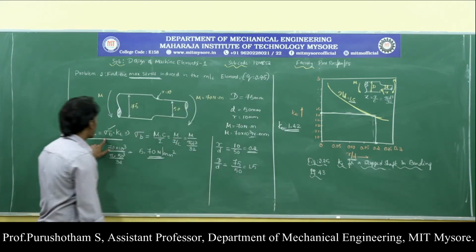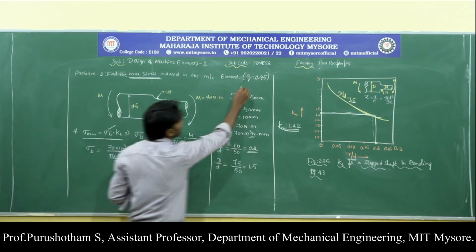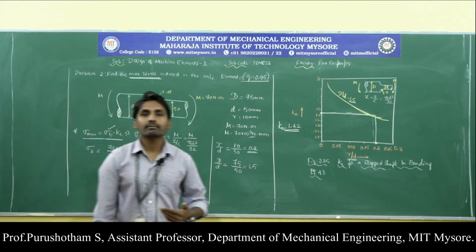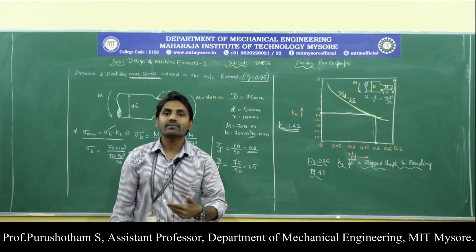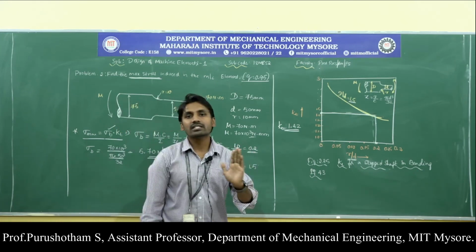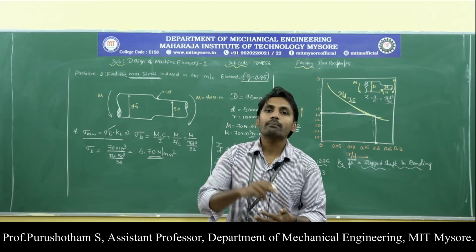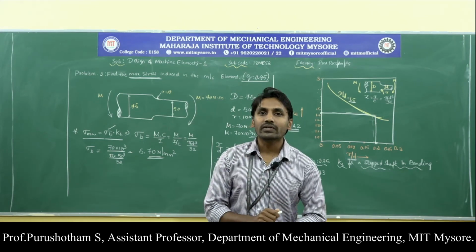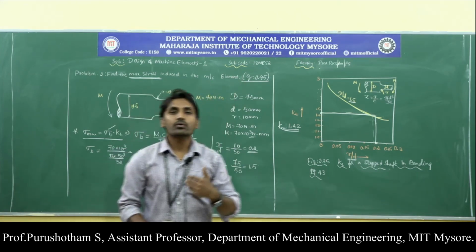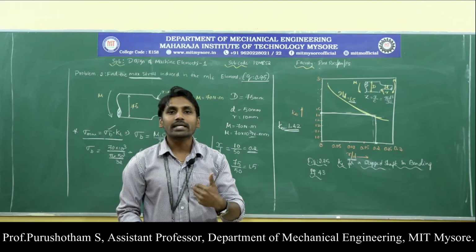So now KT value is known, sigma b value is known, but mainly one thing is given, the q value, which is equal to 0.95. That is the notch sensitivity index. That means the KT value, the theoretical stress concentration factor, only takes account of the type and size of the discontinuity. The q value takes account of the type of loading as well as the material.